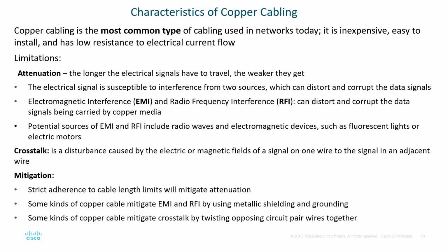So attenuation again. What we're going to learn is your cables have specified lengths that they can run successfully without incurring attenuation. If I take that cable, let's say 100 meters, and I push it past its limitation of how far the run can be, and I do not have an intermediary device in between source and destination, that opens the door for attenuation, loss of signal.